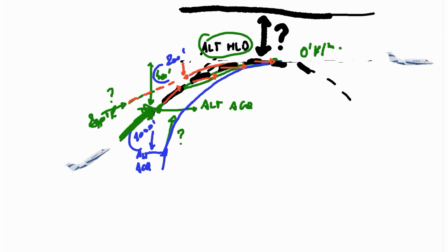If this change of altitude occurs at the moment I was with this vertical speed, what the system will do is to keep climbing with this vertical speed. So technically speaking, if I keep climbing with this vertical speed, I will reach the selected altitude at some point. So it is deemed to be a safe decision to revert to vertical speed during the altitude acquisition if the altitude is changed.